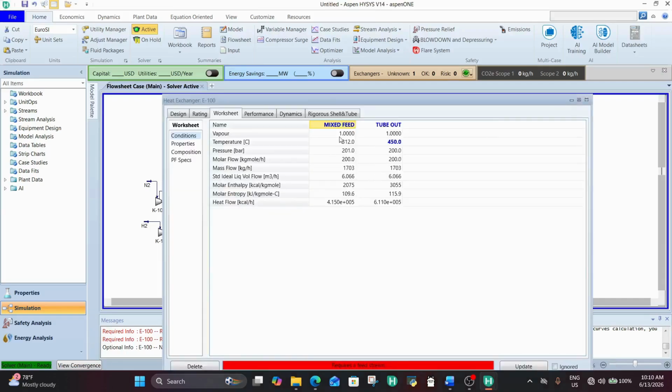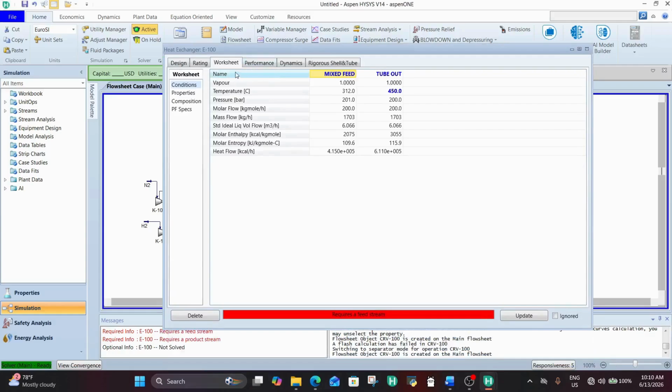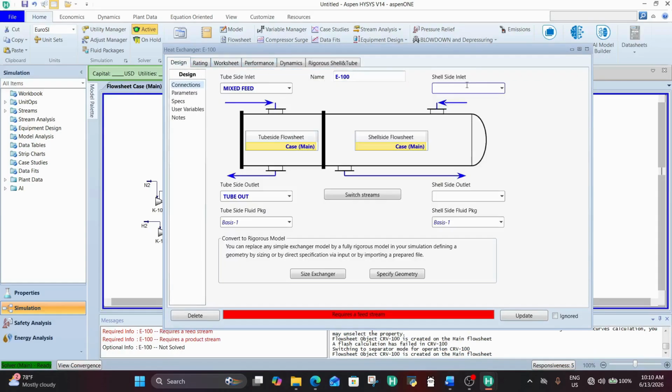So what we're going to do, we're going to plug in this ammonia and unreacted gas stream. This is going to be our shell side, which supplies it heat energy. It's all going to aid our condensation process as that particular stream loses its heat. It does well for us. We bring about condensation and we can just drop a separator to separate the ammonia from the unreacted gases. So we're going to call this shell out. Shell out. And let's see what it looks like.